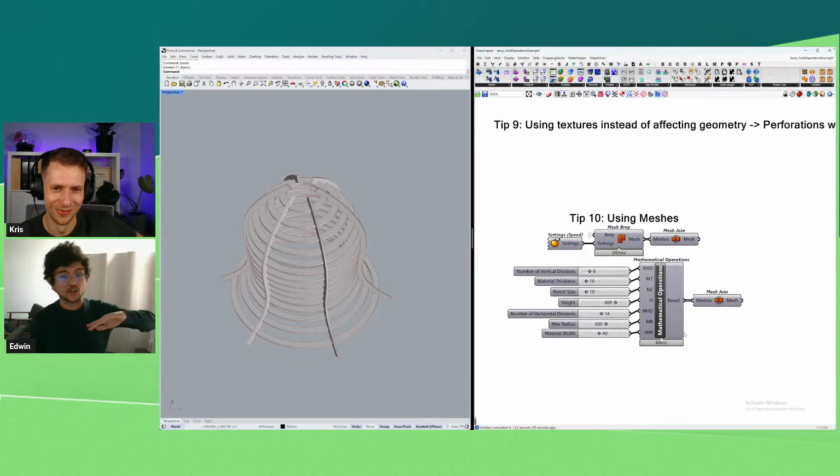Everything that you see in 3D anywhere is a mesh, because when you go to the core of how you are rendering this, your graphic card is looking for triangles. A triangle is basically just 3 points, and that's how you start to reconstruct what you are visualizing, the pixels that you are visualizing. So whatever you see in whatever 3D program, at the end of the day, even if it's a solid, what you're visualizing is a mesh.